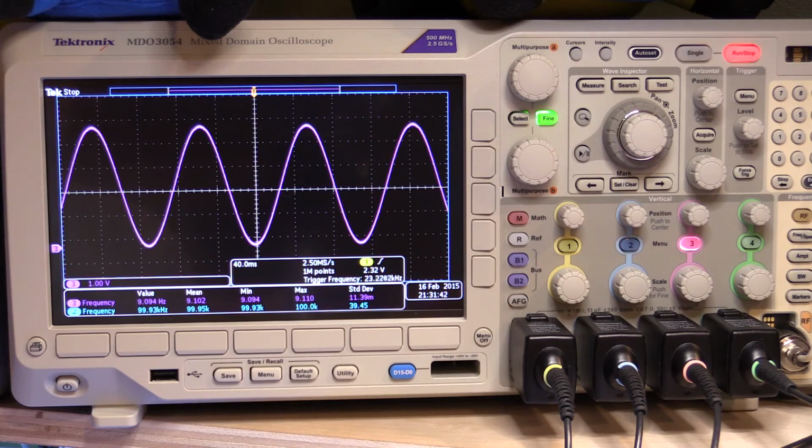Because if you remember the previous video we did, it was only using 10 bits, and if you consider how accurate this is with the external A to D converter and the D to A converter, and how stable those are, it was keeping the readings to well below a millivolt as far as stability is concerned. So let's just go back to that and have a quick look and see how accurate it really is, at least at the low end, and just have another look at the fluctuations on that.